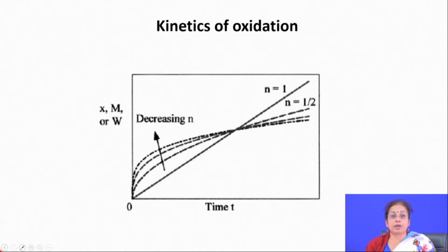You can alloy the surface by existing systems like diffusion based surface alloying or laser surface alloying treatment. So, the surface is full of an alloy which offers good oxidation resistance, and by that process you can minimize the kinetics of oxidation or the probability of the oxidation phenomenon.